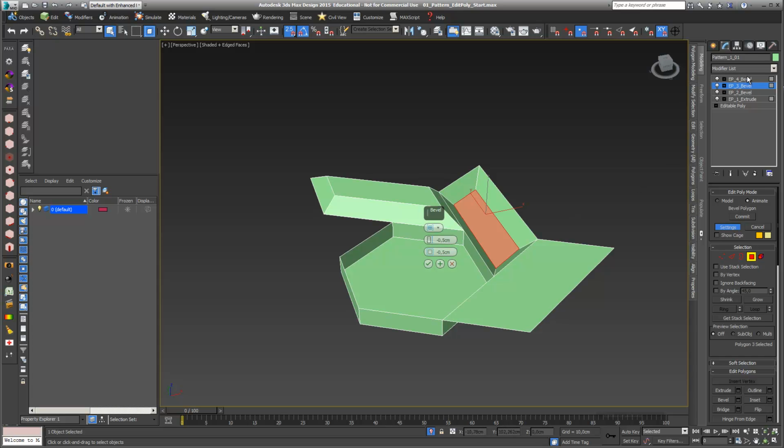And if I just select my edit poly number 4, which I do right now, I just go into my settings here and I just change it to plus again, somewhere like this, and I just use my enter key, and now I just have it a little bit like the first one, and I go and just press OK, and so I have a little bit of a variation of my basic pattern element.